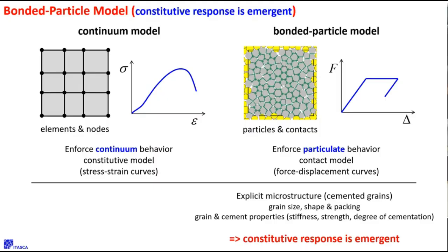And then they take specimens of rock that are big. So it's like, oh, I have an excavation that's 4 meters in diameter. Well, I'm going to take an 8 meter by 4 meter hunk of cylinder, and I'm going to perform a UCS test on that, and I'm going to use that to do the calibration. That way, at least you're matching properties that you think are important in the model you're doing.